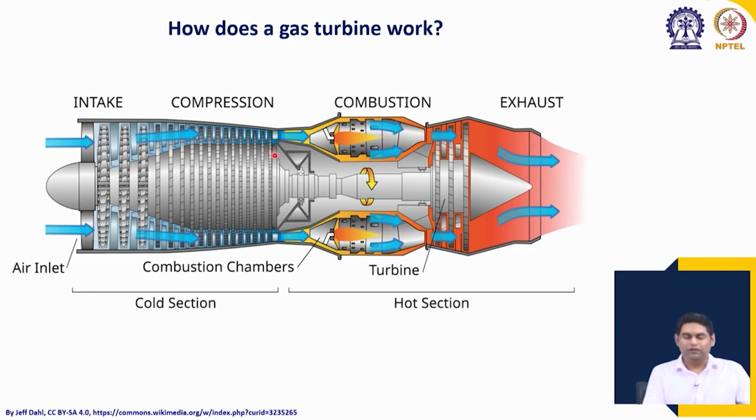Each stage is like a fan with a large number of blades. They rotate and push the air. So, this high pressure air comes to the combustion chamber, gets combusted, and hot gases pass through the turbine blades, which are also similar to fans, but here the air comes at high energy and pushes the blades the other way around, and the blades rotate, rotating the shaft. And finally, this is from a jet engine, so we have a nozzle where the exhaust gases go out at high speed.